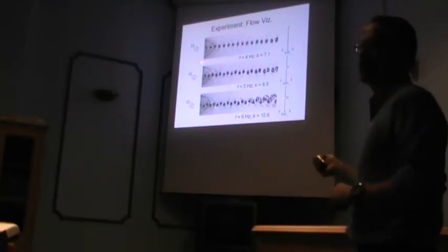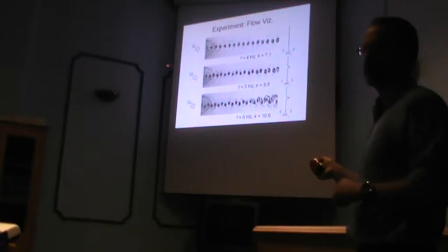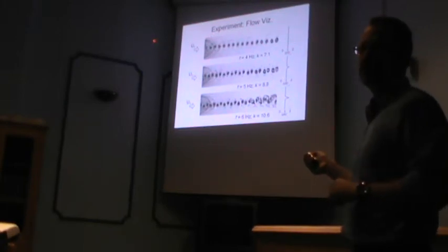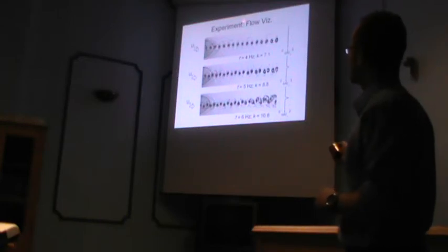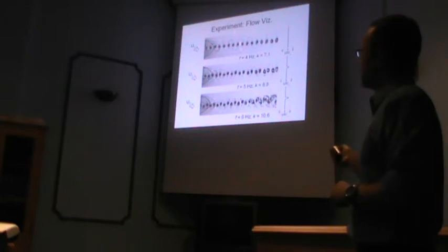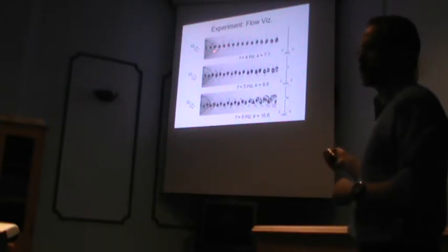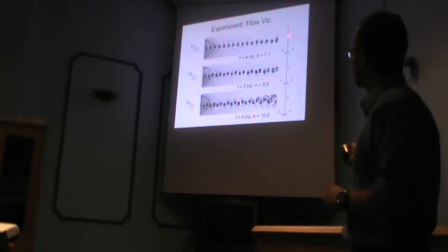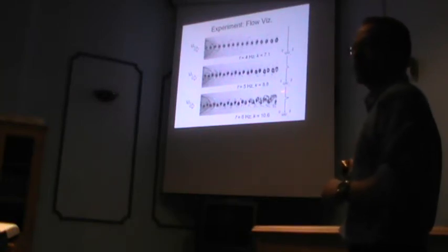What's actually missing in this slide, which I would like to describe first, is the picture of the velocity profile of an airfoil that is stationary, not oscillating. So imagine with me that you're starting with 0 frequency and then increasing the frequency. In this case where you have 0 frequency, what you expect to see for the velocity profile is in fact something that is at the free stream velocity away from the airfoil, and then you develop a wake or a velocity deficit, and then you go back to the free stream.